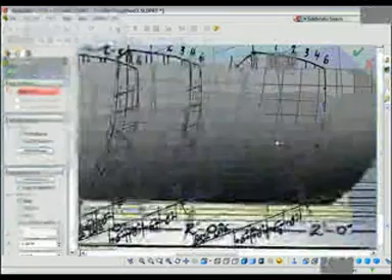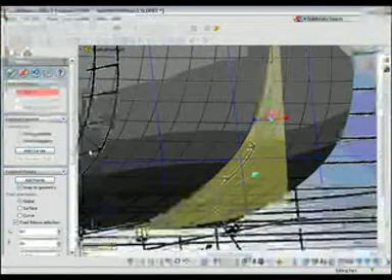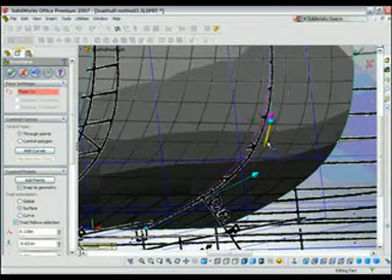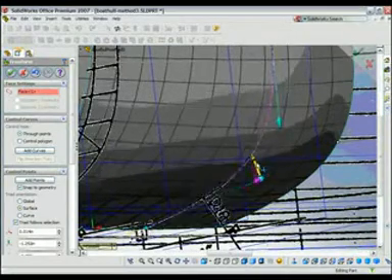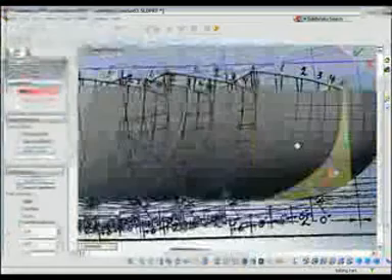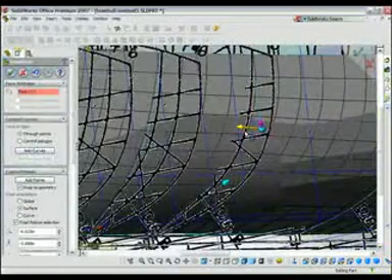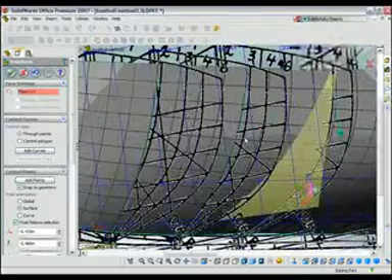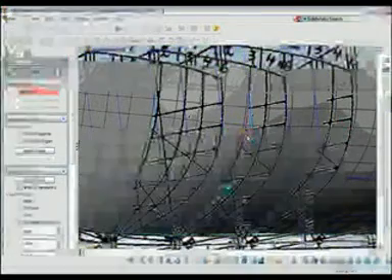Let's jump forward, and now that we have those in position, we can now adjust them to the sketch pictures that we placed. So dragging the control nodes and vectors, we can match them to our sketch picture. And we'll do that for each of these by dragging our triad and matching our sketch pictures.